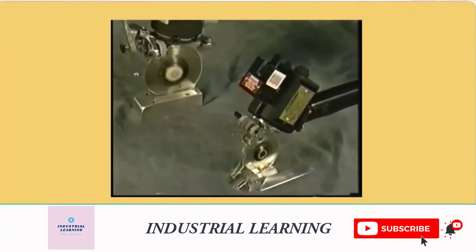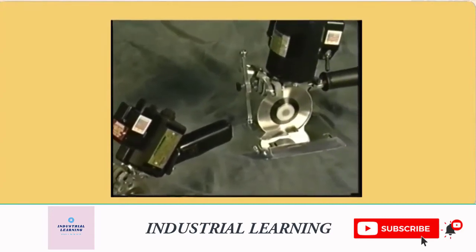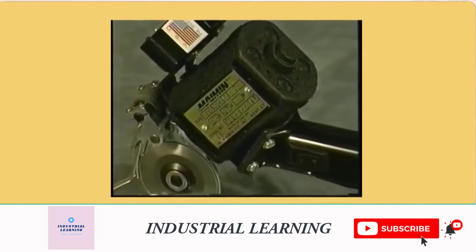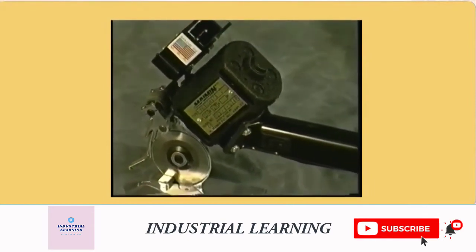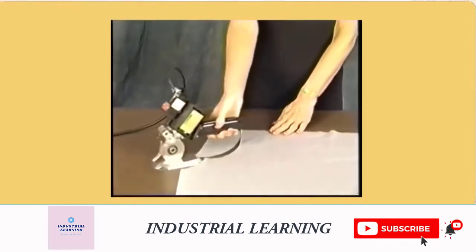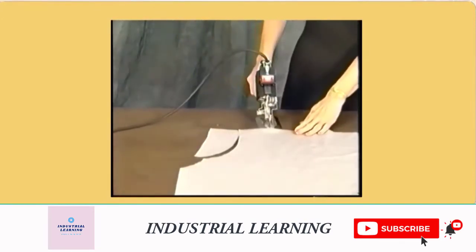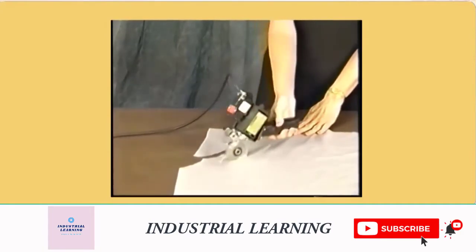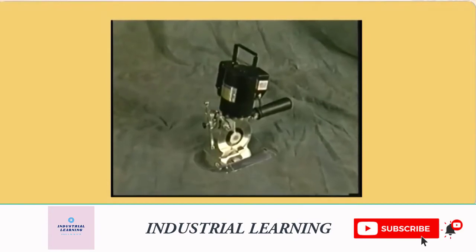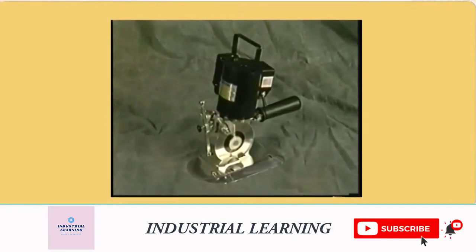Smaller cuts, but like all Maiman cutters, they are built for long life under rigorous industrial conditions. The smallest machine in this series is the RotoShear 2, which has a 2.5-inch blade and a 1/2-inch cutting capacity. This compact, lightweight, high-speed machine is used for cutting small lays where straight lines and slender curves are required. Maiman's RotoShear 4 has a 4-inch blade and runs at extremely high speeds for efficient cutting of non-fusible materials.